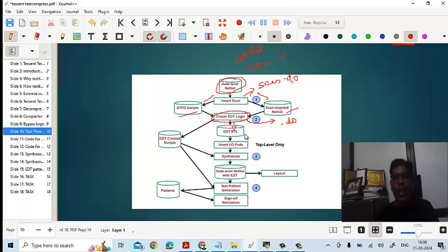Once you get this, then go to this EDT RTL and go for synthesizing it using the Synopsys tool. Here the output of this EDT logic insertion is fed as an input for synthesis. Here we get this EDT generated script. All this will be taken as an input, and this synthesis in Synopsys will create a gate level netlist with EDT insertion.